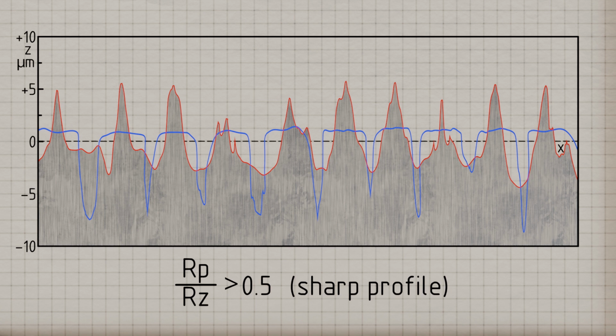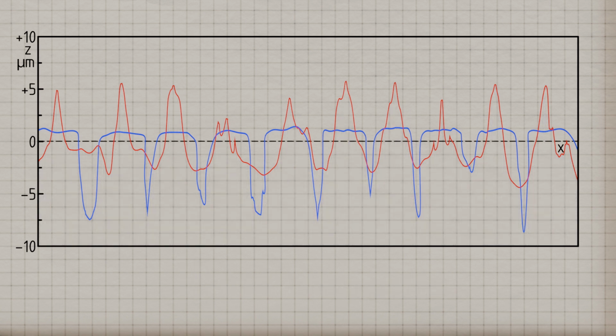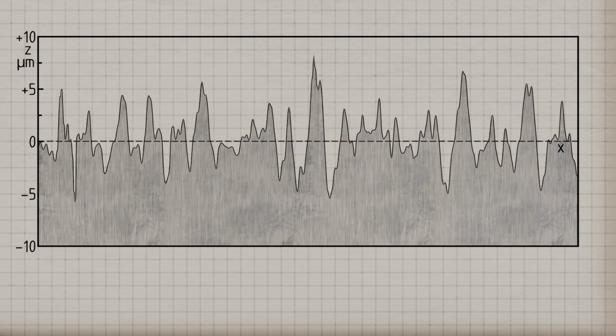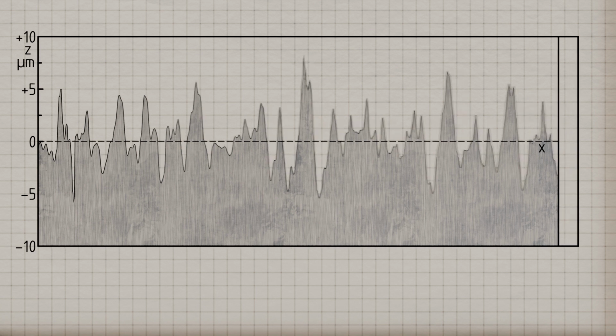This example clearly shows that a single parameter is generally not sufficient to fully characterize a surface. In practice, however, usually only one parameter is specified, because typical manufacturing processes produce certain characteristic roughness profiles, allowing the surface to often be approximately described by just one parameter. The bearing material portions of a surface, as a function of surface depth, can also be explicitly represented in a diagram.